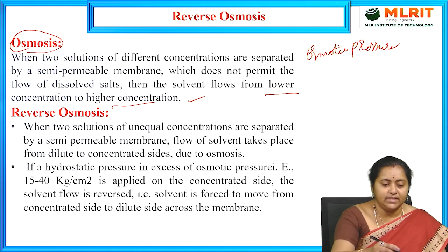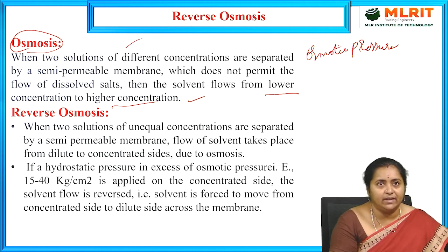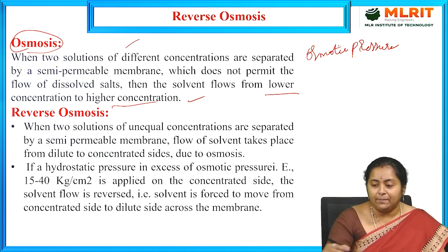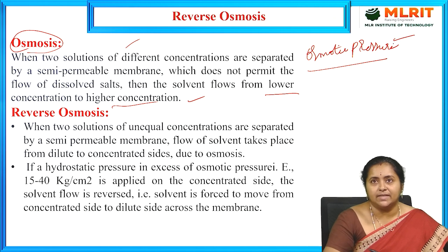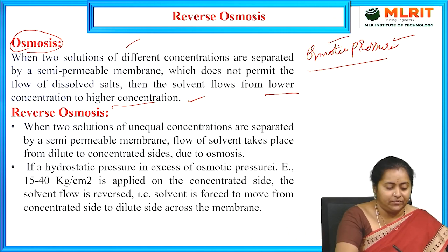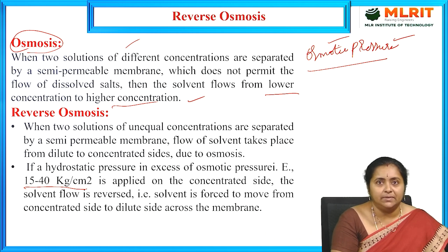Now, using this principle, if I make some changes, that means if I supply hydrostatic pressure in excess of this osmotic pressure, let it be like 15 to 40 kilograms per centimeter square.